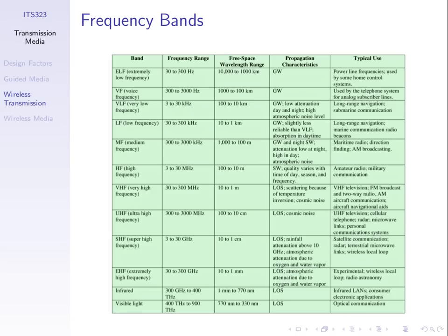But when it hits that water, the signal gets weaker, it attenuates. So if it's raining a lot and the signal goes through, it may be that the signal received is very, very weak. And on your TV, you may see some disruption or some poor quality signal, poor quality image, because the satellite signal at those frequencies is attenuated by water vapor in that case.